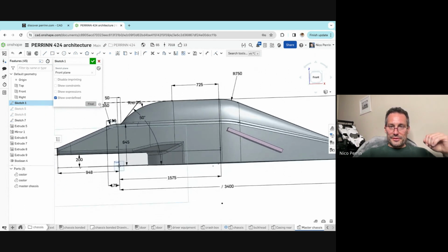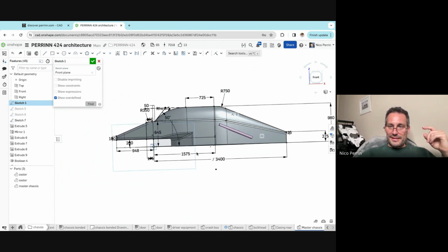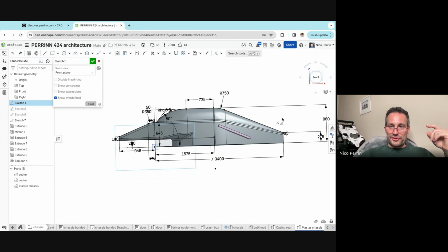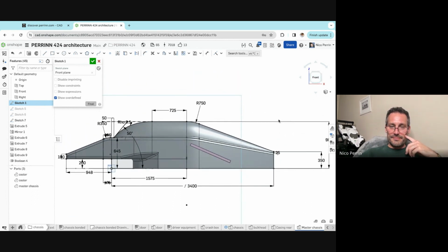You could imagine doing some big changes there. That's the radius connecting back to the engine cover. Let's imagine the engine cover is going higher. We need more space for what's under the bonnet here. I typically go here and say, okay, I'll add, I'll go to 350 here, and the whole back of the car is going to increase in height. You can see that. Come back.